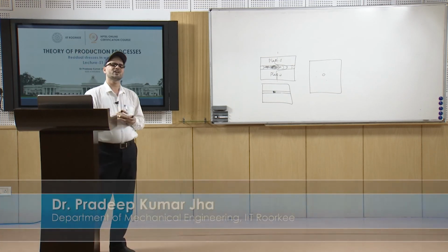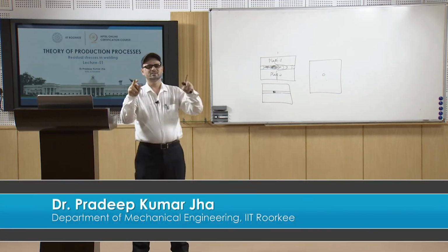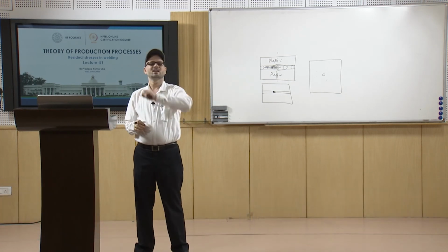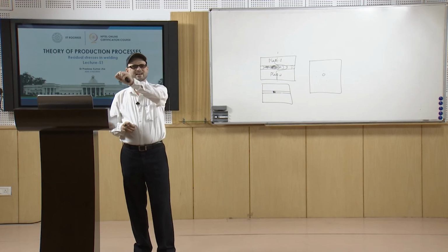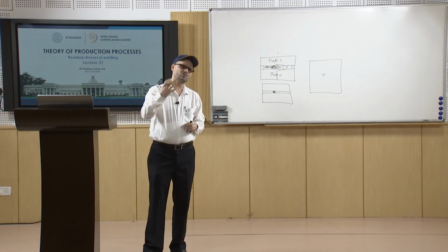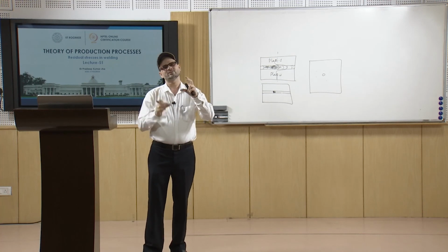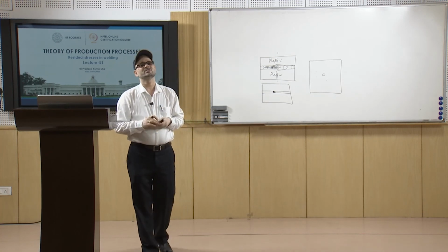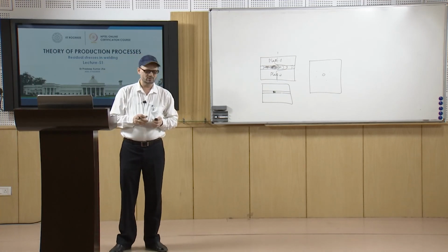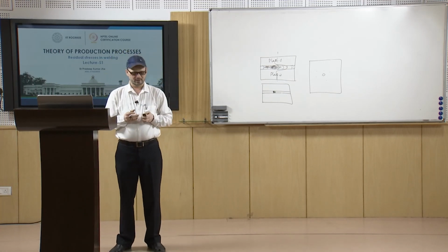Another method is the strain gauge method, where on the surface, again you have the drilling at one point, and you have strain rosettes or strain gauges at the points, and then the value of strain will be calculated after drilling, and based on that you can calculate the stresses. So, this way you can calculate these residual stresses from the specimen. Thank you very much.